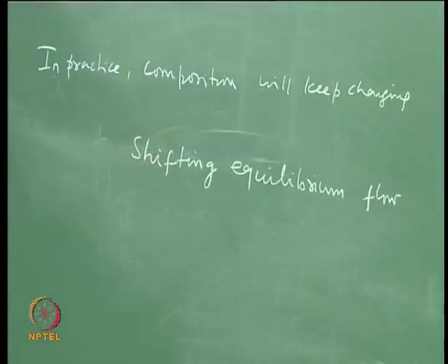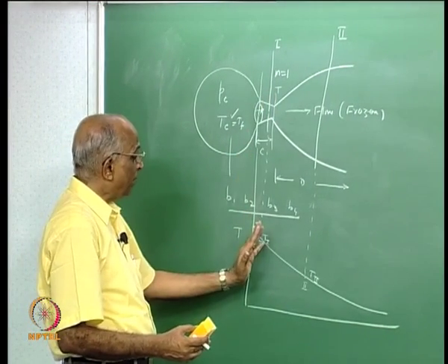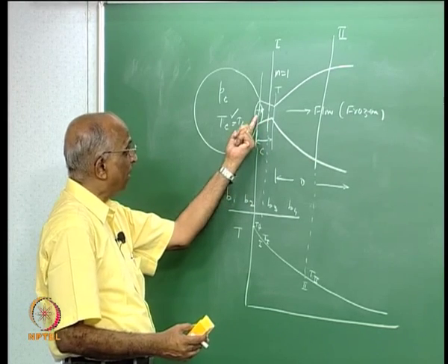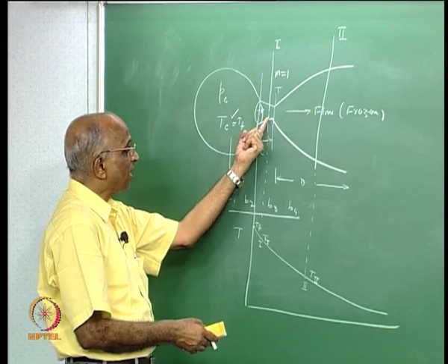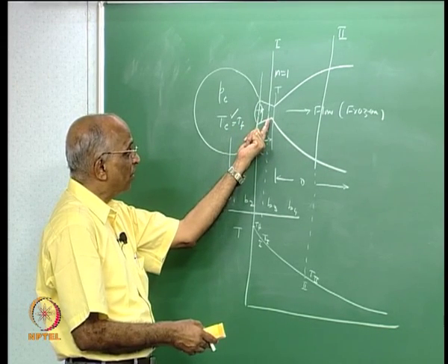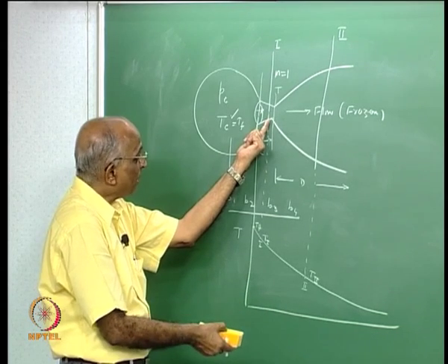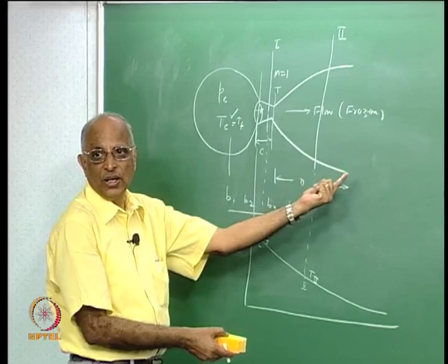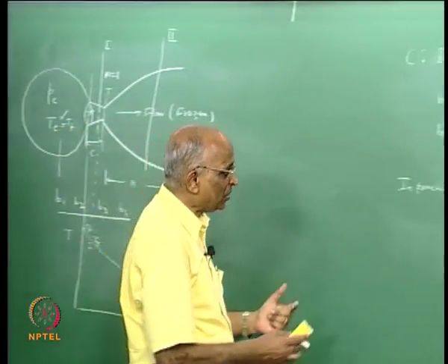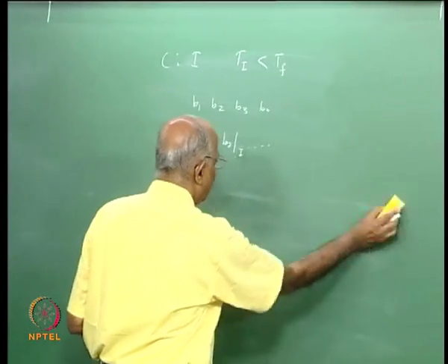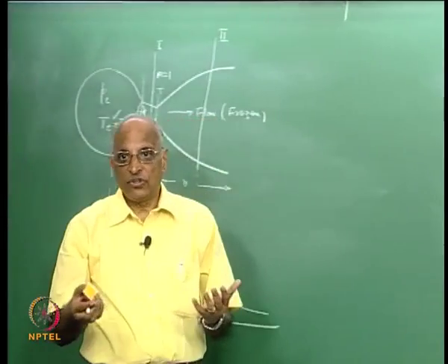Well, to solve this is extremely simple. I go to the next section, I find out what will be the temperature for this particular expansion, assuming the values of gamma corresponding to the earlier section. At this point I find out the value of the new species, I revise temperature again, revise products again, and so on. I can do this using a chemical, or let us say a shifting equilibrium.